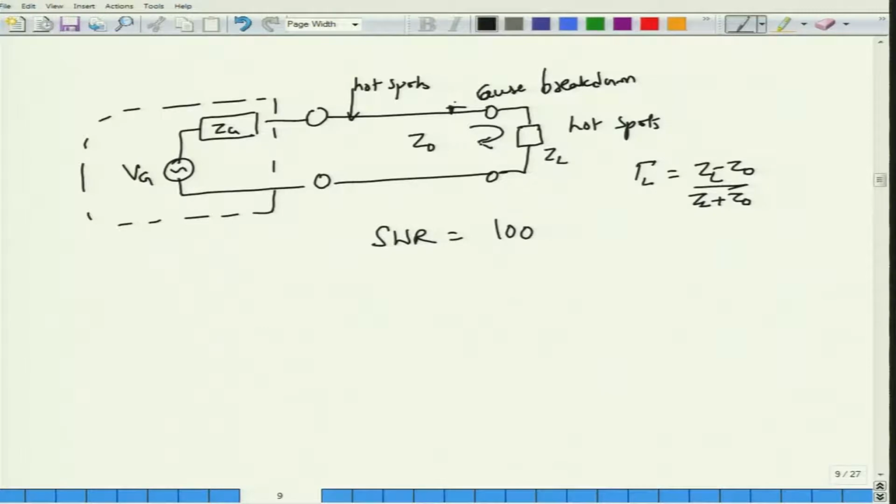So, you would have created a reflection here, and when this voltage comes back, we have not really talked about it, but you can easily estimate by switching this Vg onto this side and realizing that if Zg is not matched to Z0, there will be one more reflection. In fact, these multiple reflections in the steady state are what cause the standing waves, and we should not have them because they create voltage hotspots and do not allow maximum power to be transferred.